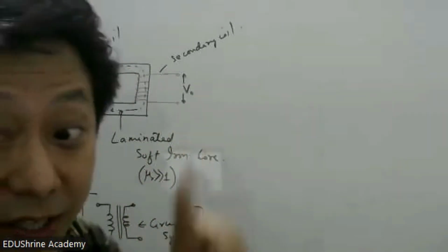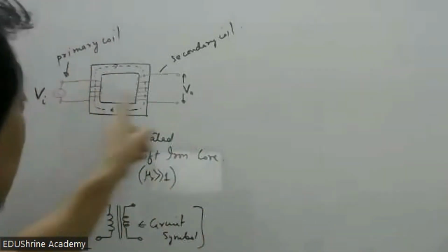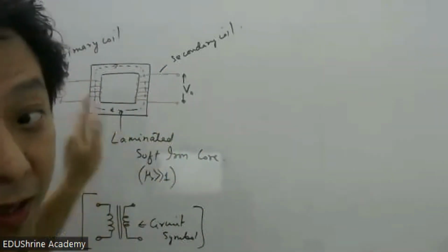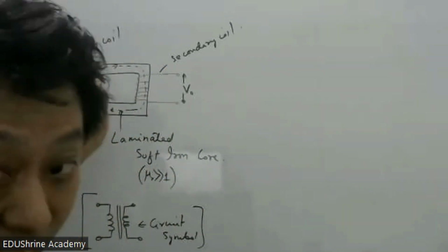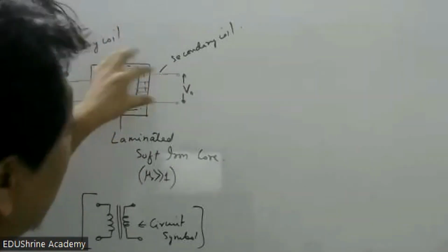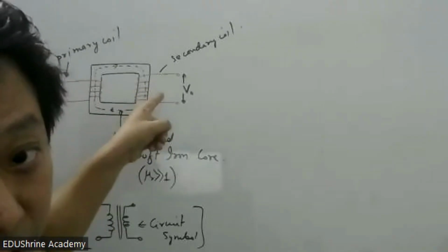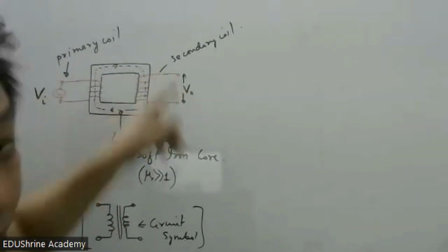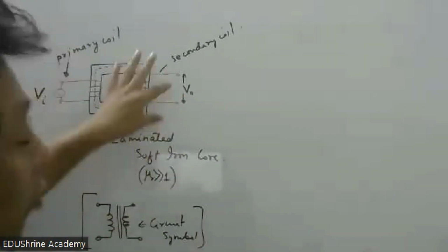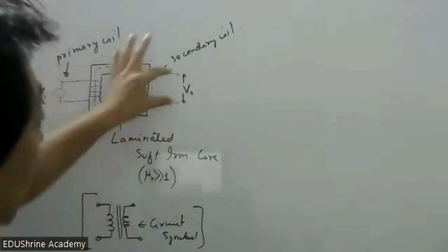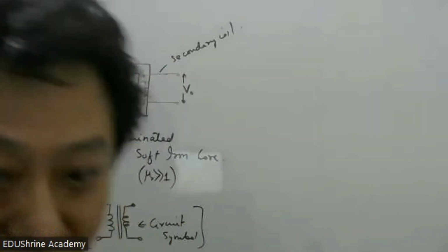There is mutual inductance here if you see carefully. First of all, there are two coils, and change in current in one coil is inducing not current but voltage. Why no current here right now? Can you guess? Why no current here right now? No circuit. Because it is open circuit right now, right? But voltage can be there, right? Sir, once more, can you explain?